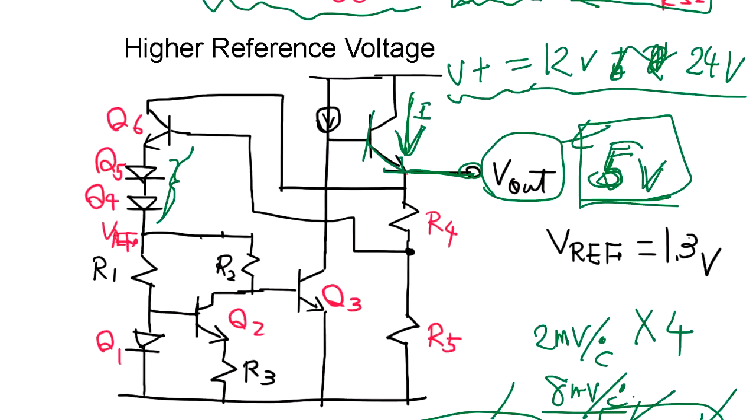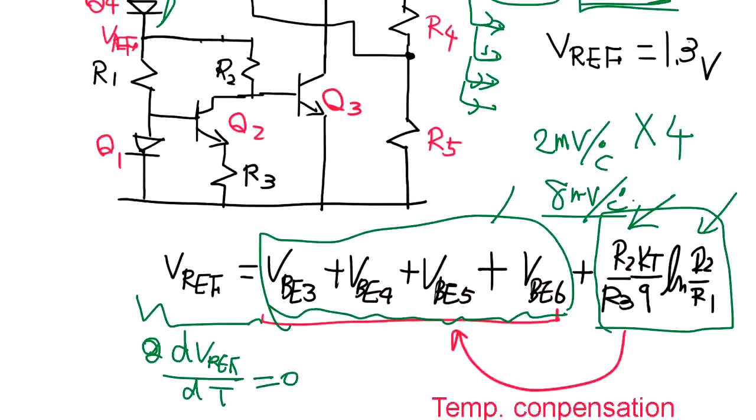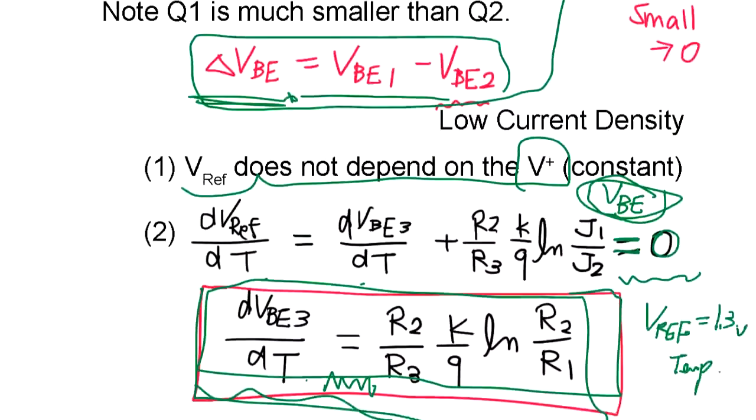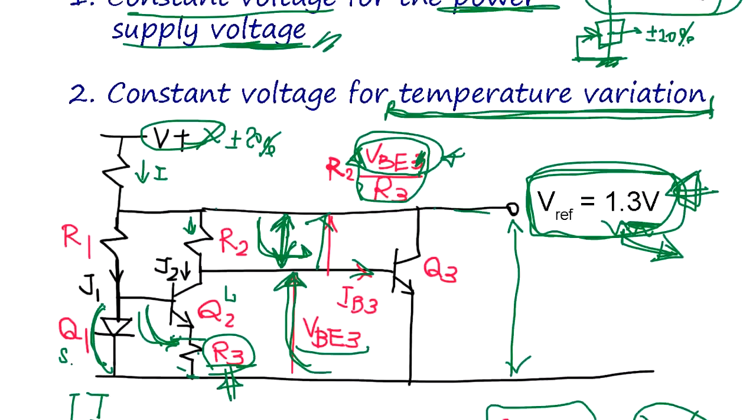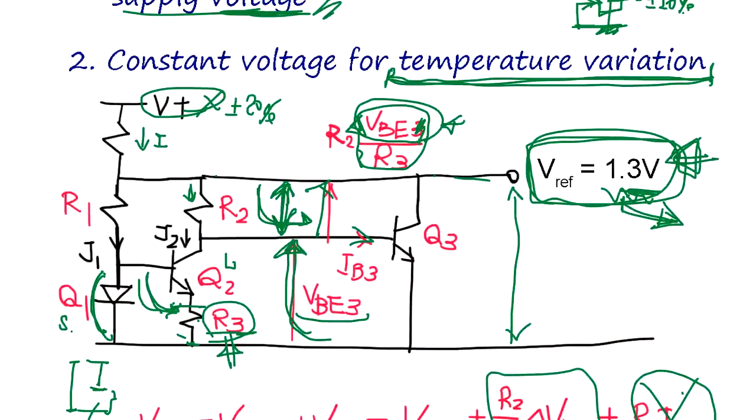So even if you drive many circuits and each one has a current, it's okay, it doesn't affect this guy, right? So you always configure the output like taking it from the emitter. We talk about this later too. Okay, so that's the very important band gap reference technique in analog design, and you have to know this if you do IC chip design.